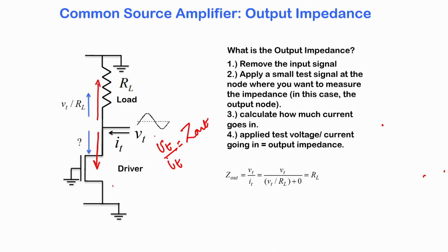The MOSFET is in saturation, and any fluctuation at the drain to source node is not going to create any current. If the MOSFET is in saturation, the fluctuation in VDS really does not matter. There is going to be no current if it is an ideal MOSFET, because we are not considering channel length modulation. If we consider channel length modulation, yes, there will be a current.